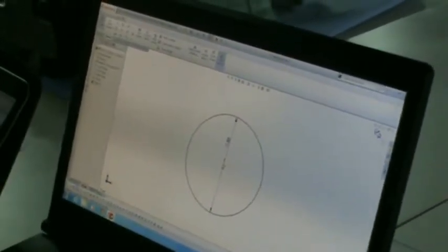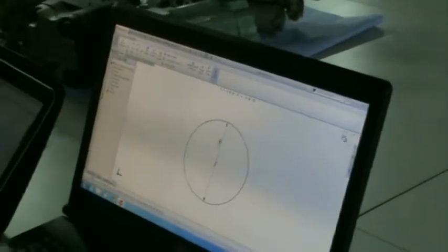I also tell my students, when you have no fully defined sketch, it's not finished. You may not make a feature of it, because it's not finished. It's too dangerous to have damage after. Yes. You can say yes, it's a good one, and then maybe sometimes after a few steps, I can finish the sketch. Okay.